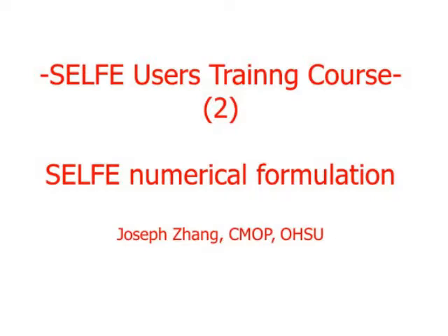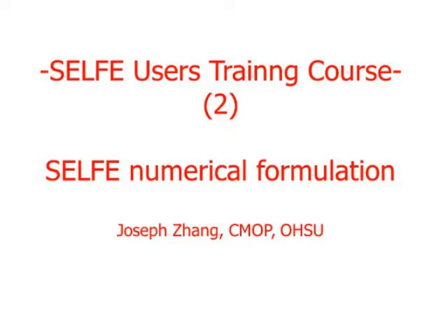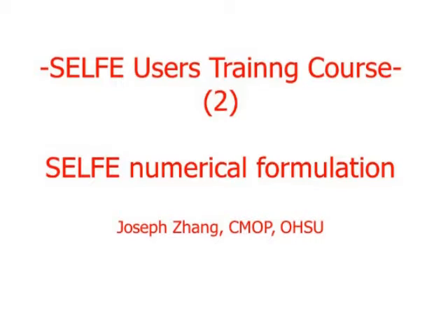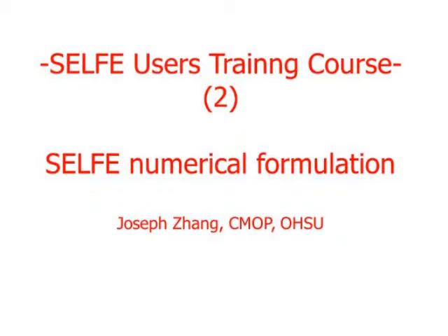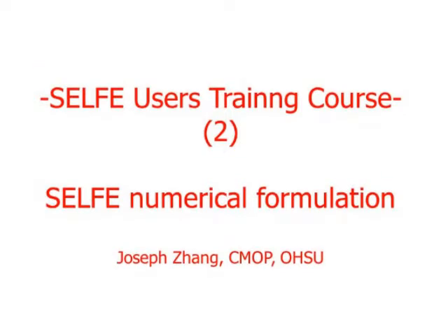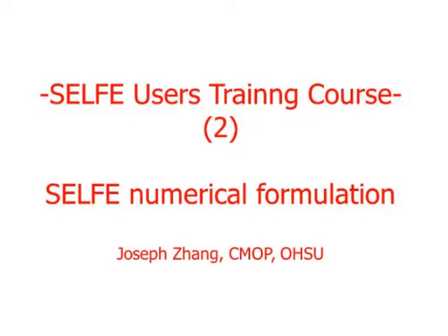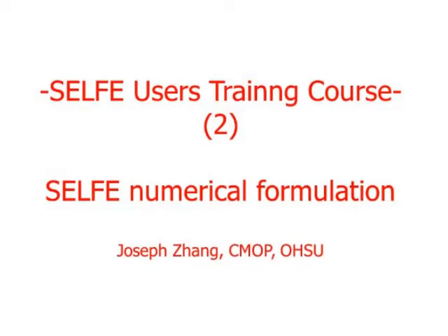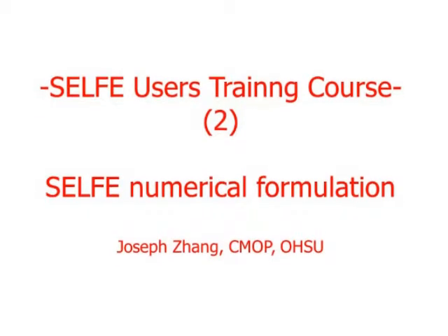The way we evaluate this baroclinic term depends on what kind of algorithm you use to solve the transport equation. I haven't reached the point to tell you what method we use, but very briefly, to give you a heads up, we use two methods to solve the transport equation. The first one, we just use the traditional ELM to treat the advection, whereas in the second method, we use pure Eulerian methods, that's upwind and TVD methods.